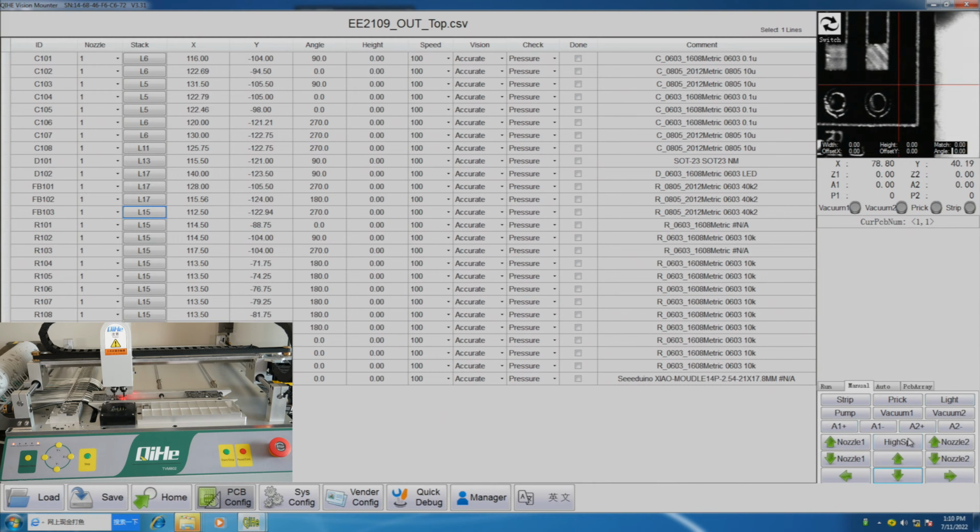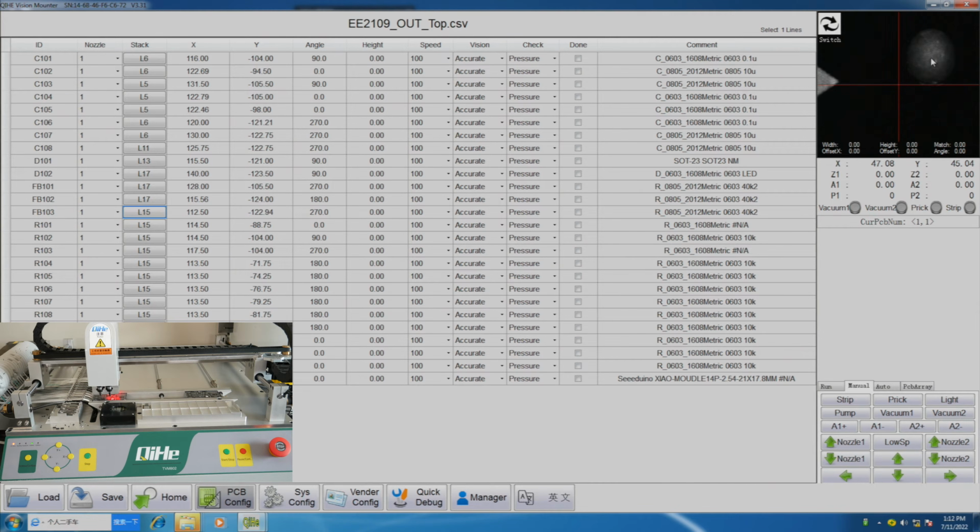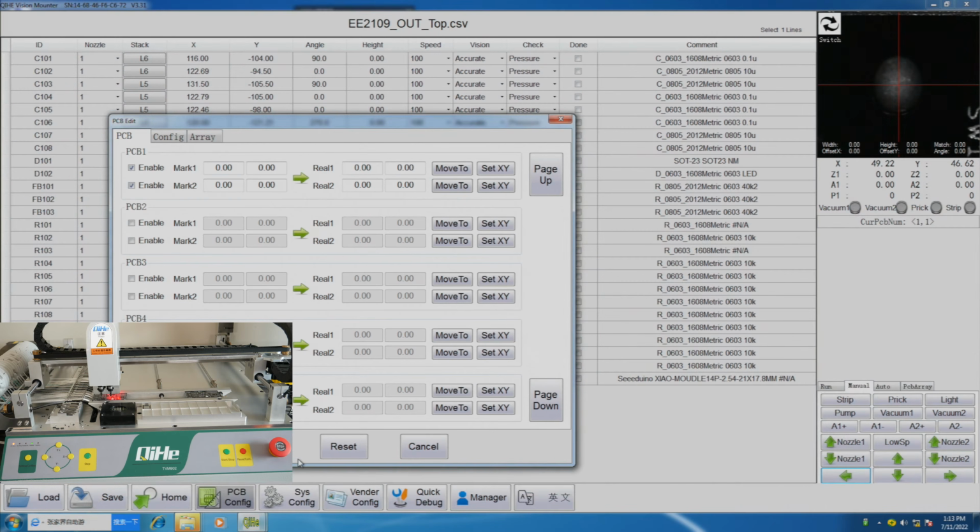All right, I'll switch to low speed. Now, this is a perfect example of why fiducials are incredibly important. Doing this without a fiducial, that's not great contrast. This might not work. We might need to pick a pad to reference, but we'll give it a try, and we'll see if it fails. So we'll call this